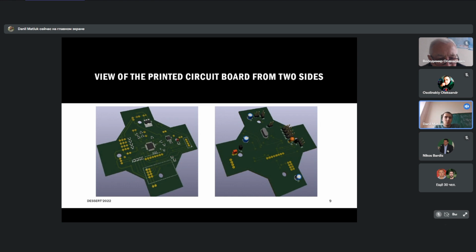The board is based on an STM32F4 family microcontroller and has a specific groove shaped to be placed on a specific frame model. The board's size corresponds to the dimensions of the quadrotor chassis, which also made it possible to place all the necessary components on it, thereby reducing the number of wires to a minimum and avoiding an additional servo board.